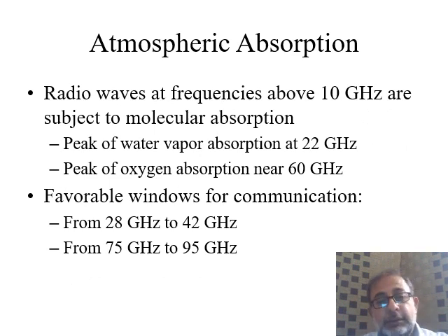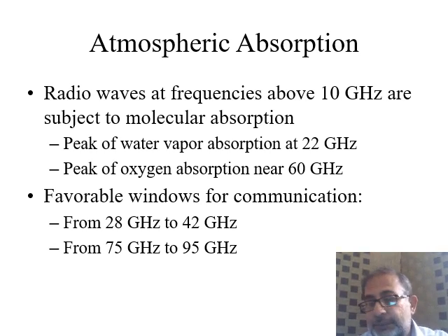Now, what is atmospheric absorption? Above 10 gigahertz, molecular absorption takes place. For example, the peak of the water vapor absorption is 22 gigahertz. Peak of oxygen absorption is near 60 gigahertz. So we need to avoid these two particular frequencies.